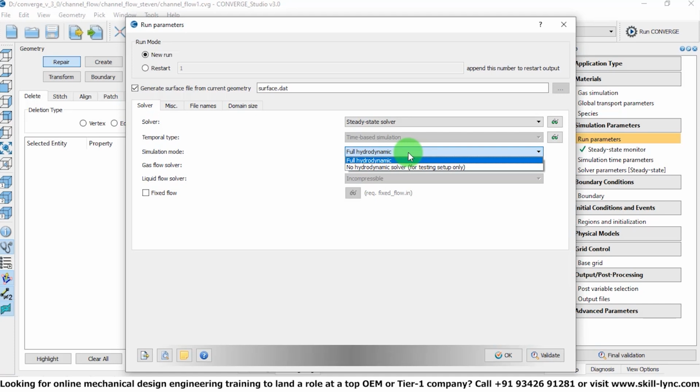So in those cases, it is always a good idea to generate the mesh first. Why? Because while generating the mesh, if there is some problem, let's say you flag the boundaries incorrectly, and because of that the mesh is getting stretched or overstretched, and because of which intersections are happening, or there are some parts which are intersecting with the other walls, right?